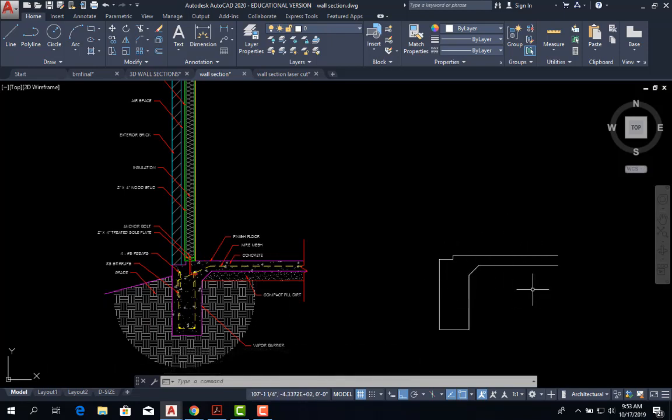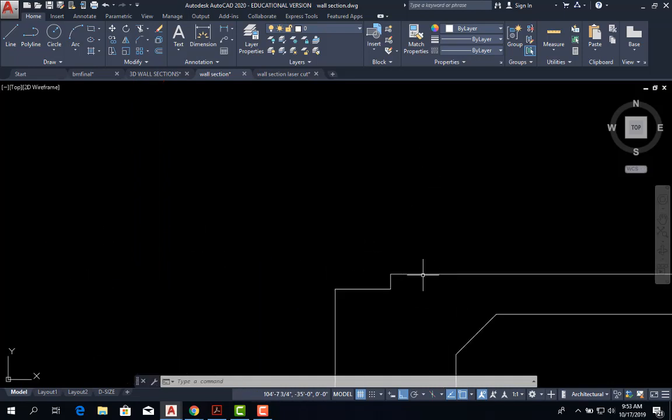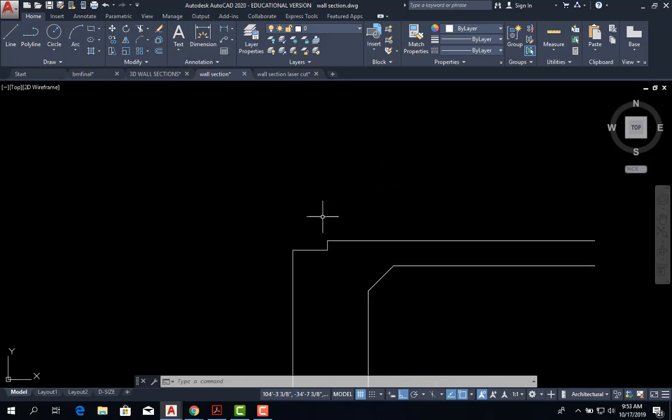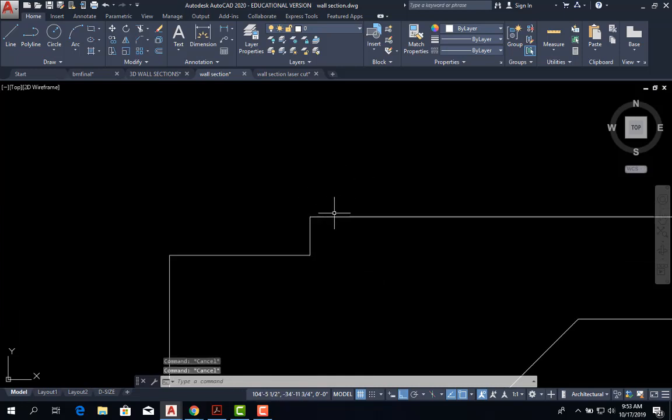Okay, again, we're doing this so you can get the members ready, and then we'll finish it in class. So now I want to do the actual wall stud, but first at the bottom we're gonna have to do our sole plate. So that's 3.5 by 1.5. In reality, we call it 2 by 4, but in reality it's half inch less, so it's 1.5 by 3.5.